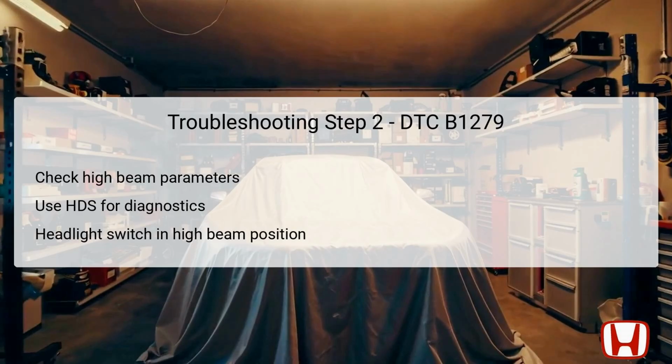If both indicators are illuminated, you need to check for potential shorts in the wiring. However, if both indicators are not illuminated, it suggests an intermittent failure in the system, indicating that the system may be functioning correctly at that moment, but could fail intermittently.